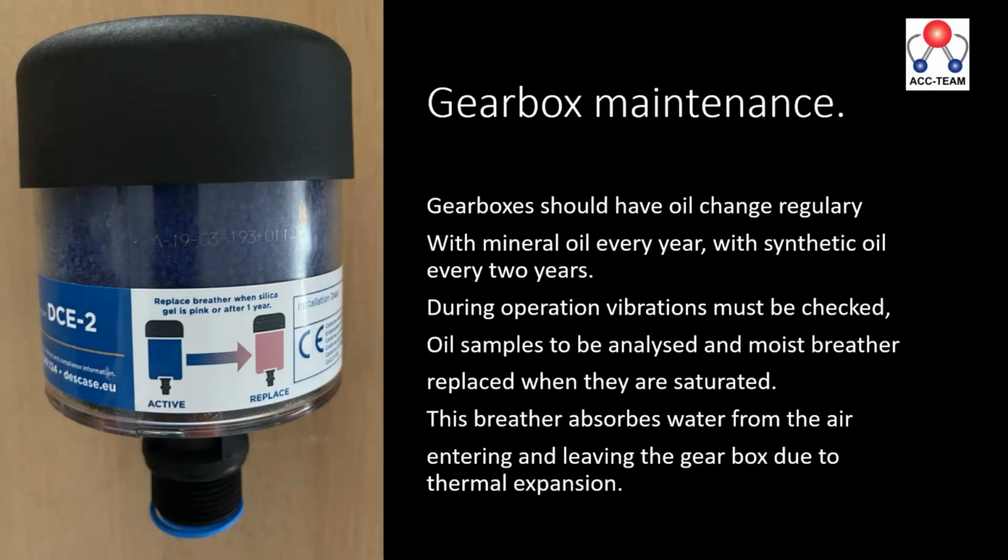What we normally advise is that if you use mineral oil, you exchange the oil every year. If you have synthetic oil, you can do that every 2 years. And when you do this, at the same time, check your vibrations. Take a sample of the oil to see if there are no funny materials on the inside. That's one of the first steps to prevent your gearbox from failing.